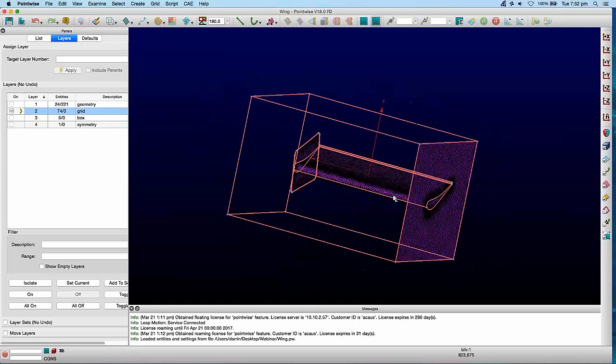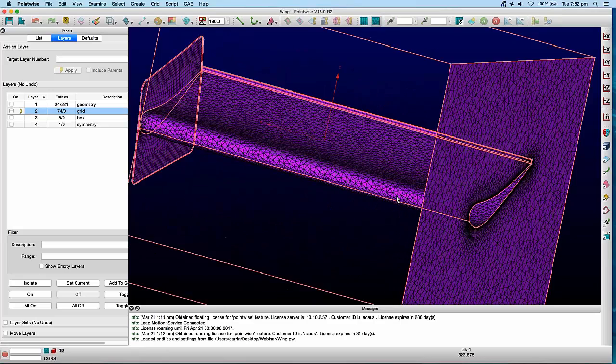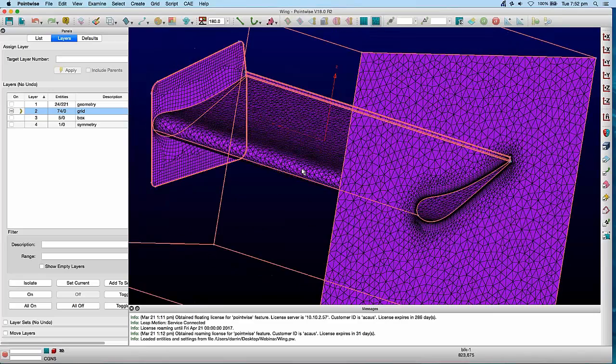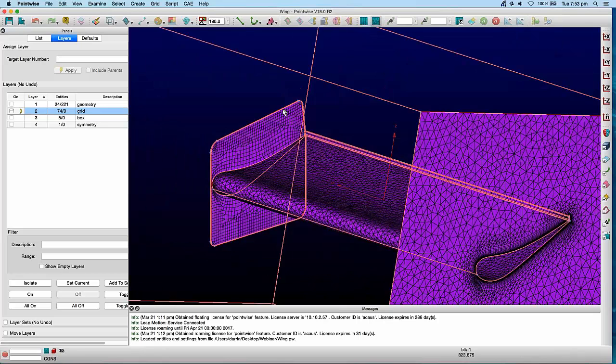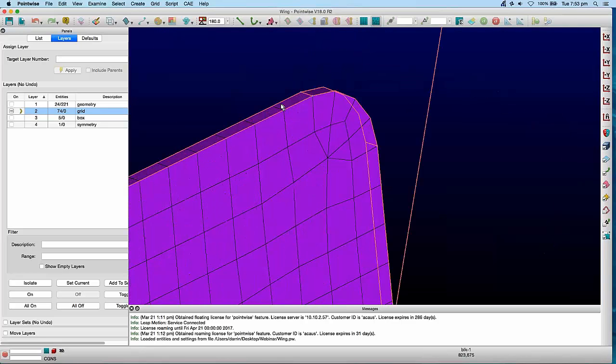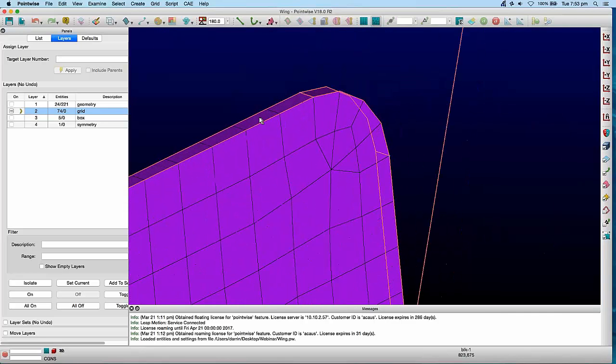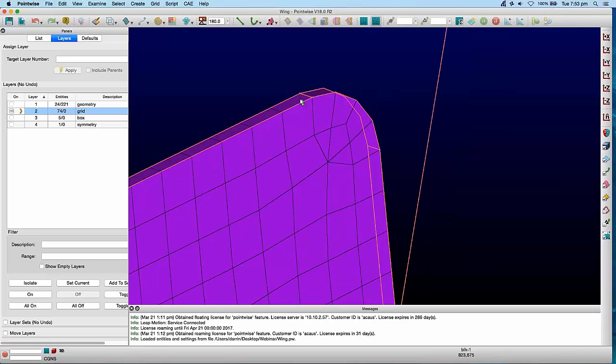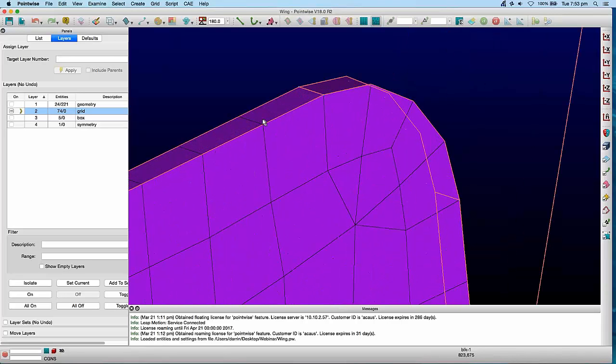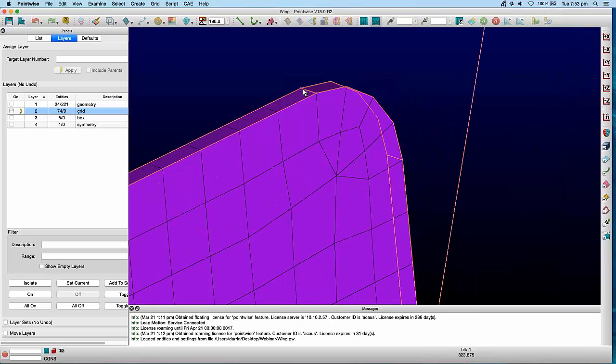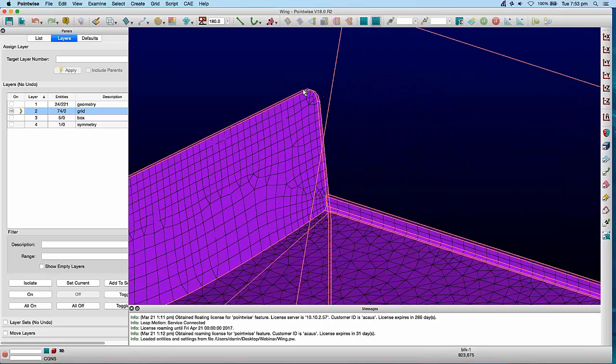So what we start with is putting a surface mesh onto the geometry, and I'll just show here. The end plates have a thickness of a few millimetres. We actually mesh those, and you can see it's not fully resolved here because it's only one element thick, but yeah, they're in the geometry.